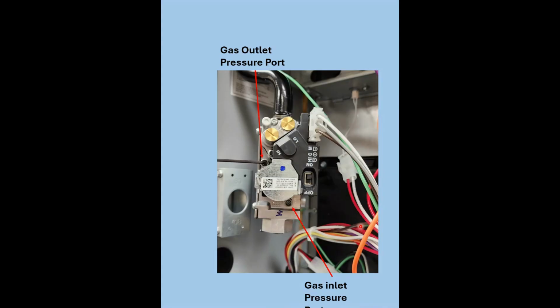At least keep it right in your manometer, or if you use a spring pressure gauge, like from a long time ago. I mean, they all work, but keep that little hex head wrench in there because that's a difficult size to find. And you're going to verify that inlet and outlet gas pressure.